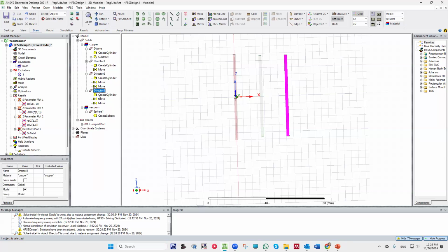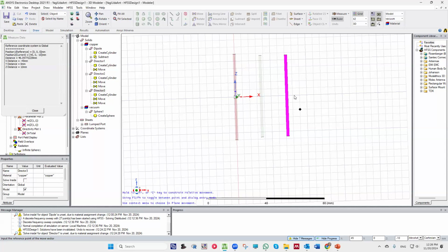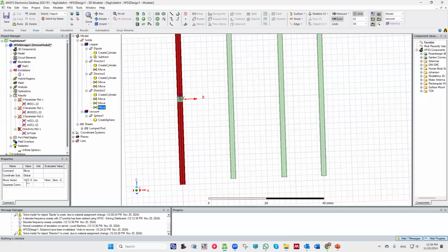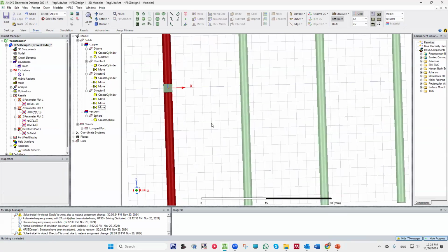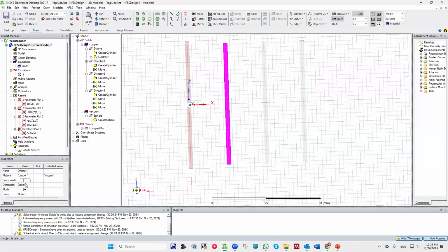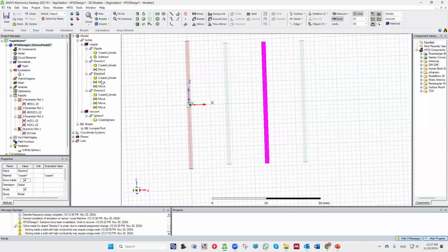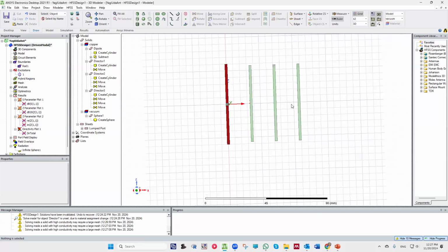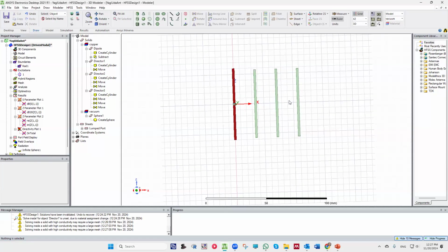Again, highlight, insert, move from the center by another 18 millimeters. Okay. We can also enable solve inside because this is a realistic metal. So this solving inside will correctly solve the characteristics like radiation efficiency of my antenna.